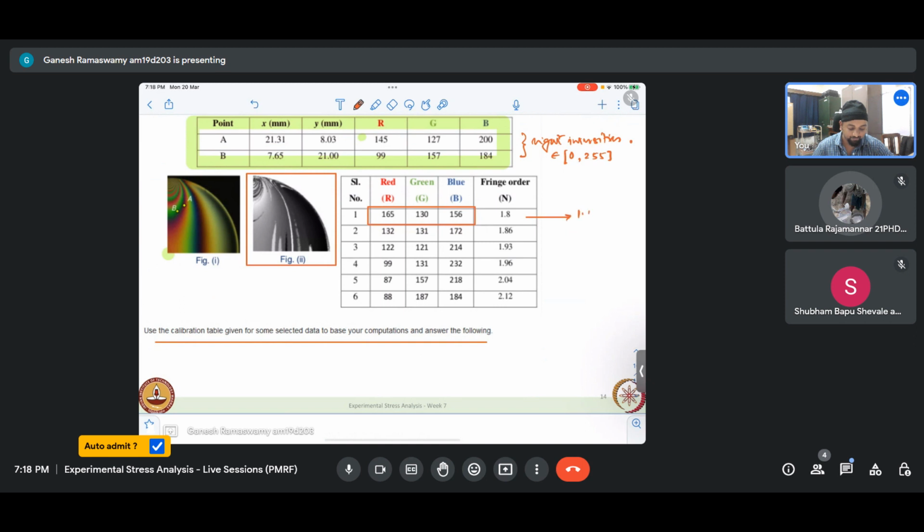This is known from a known problem, namely the 4-point bend specimen where the fringes are straight and horizontal. So essentially, once we know the load we have applied, we can see what the stresses are being formed, and in case of a 4-point bend specimen, we know at the neutral axis sigma 1 minus sigma 2 is 0, so it will be black in color.